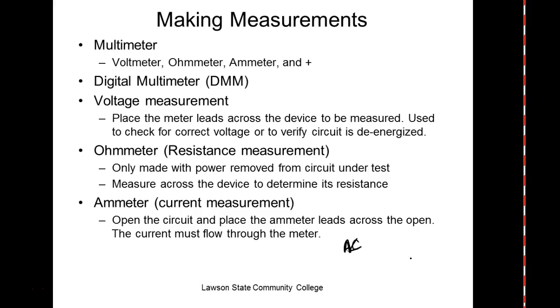Then we have what we call electronic overloads. Electronic overloads usually use something very similar to a clamp-on ammeter. It uses what we call a current transformer. They call them CTs, which basically works on the same principle. With a clamp-on ammeter, you're not actually measuring the current, you're measuring the strength of the field. We got a couple of clamp-ons. They're still called clamp-ons, but those are not ammeters. Those are clamp-on ammeters, right?